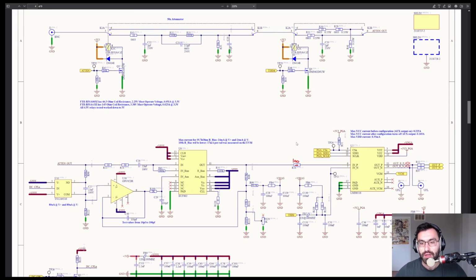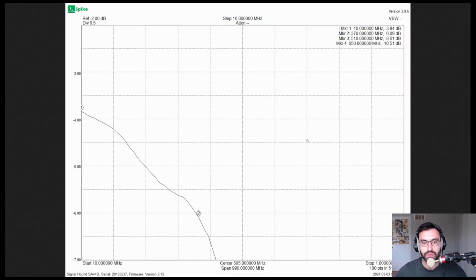So I figured, okay, we are going to need some sort of series resistance here. If you look into the data sheet, it will peak when driving a capacitive load, so that made sense to me. And 100 ohms was way, way too high.